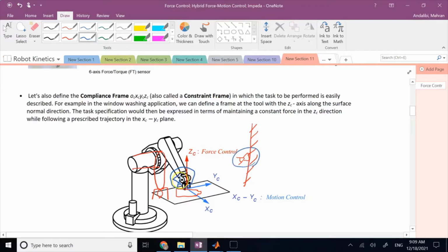The bad thing is, as you get closer to the object or further away, the field of view can change drastically. Okay, and the rotation matrices and everything that you had for the end effector, the position of it that you had from forward kinematics, they will be included in your relation for computer vision. Because again, the position of this with respect to that camera is not going to be fixed. It's going to get closer, it's going to get further away, and the field of view, right, if this is